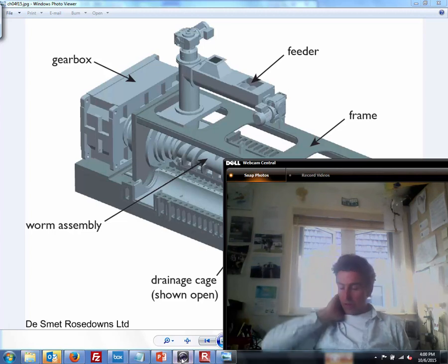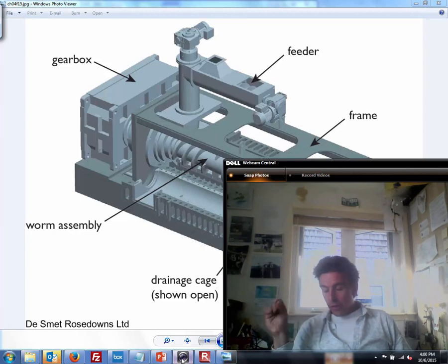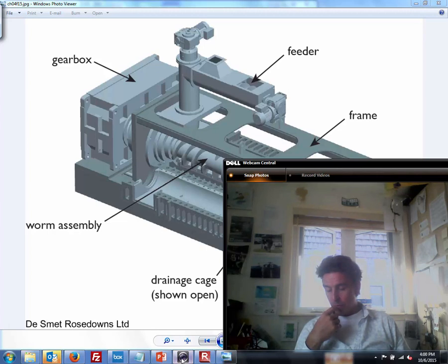Okay, and a complete industrial gasification process using oxygen can produce a stream of carbon monoxide and hydrogen, as we just mentioned, with any other impurities such as tars, ammonia, and sulfur compounds being chemically removed. This is known as synthesis gas or syngas. So taking out the sulfurs, the ammonias, and the sticky tars.